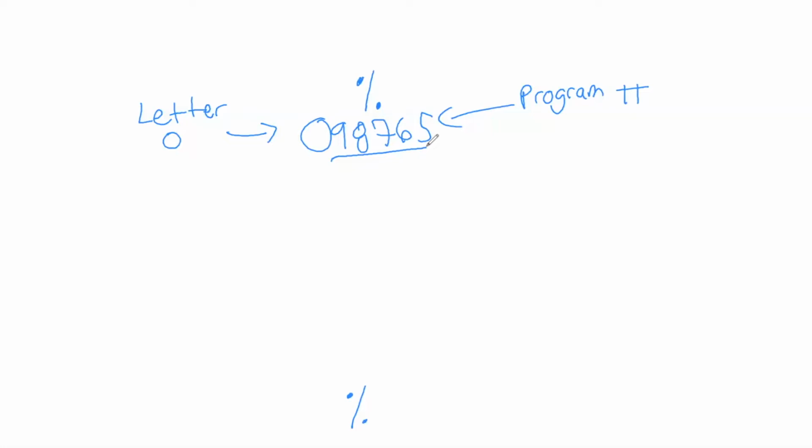Right. The next line is a little bit of a difference in opinion on what comes next, but for our class and going forward with how we're going to write programs, we're going to have a safety line. These commands will be at the beginning of every program, and this safety line will ensure that we're in the correct programming mode, measurement system, coordinate plane, and will cancel any cutting actions to prevent any crashes or unnecessary cutting. Our safety line will come next. This will be in every program.